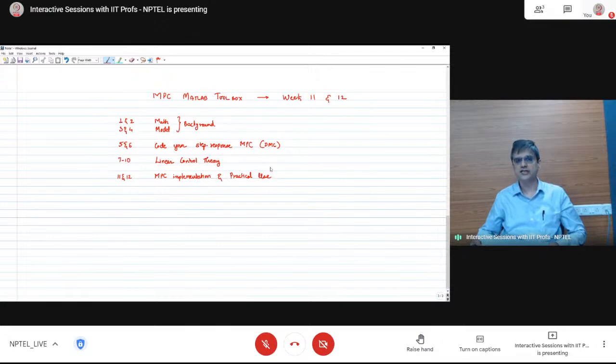The other context is that MPC takes a lot of simulation time to run. So how can we reduce the simulation time by using certain strategies? For example, nonlinear MPC might take seconds to minutes to give one single control action, whereas faster MPC works in the time scale of 0.1 to 1 second.